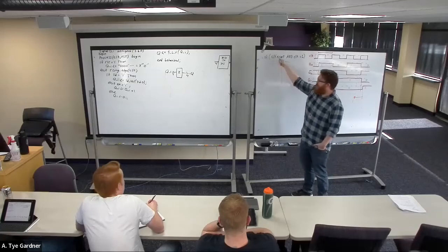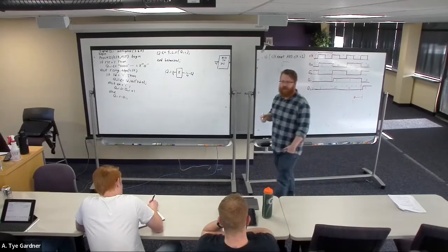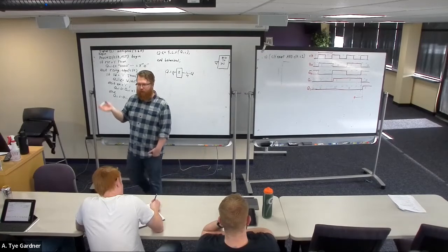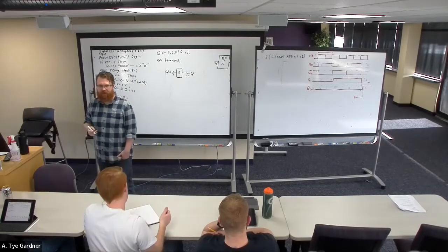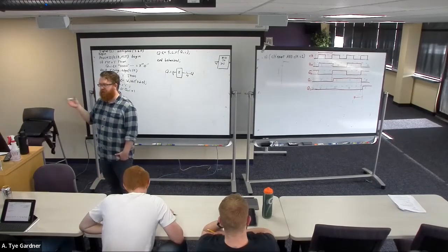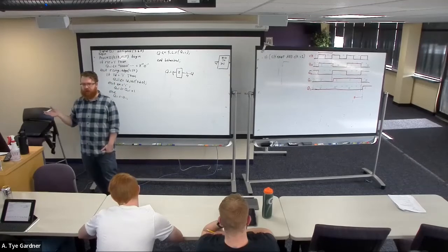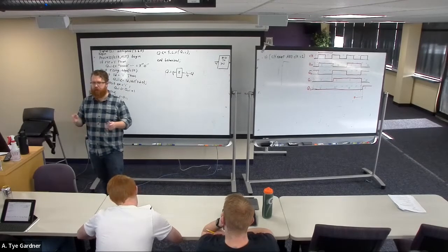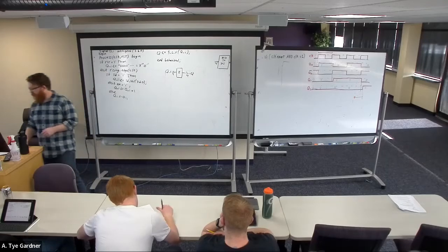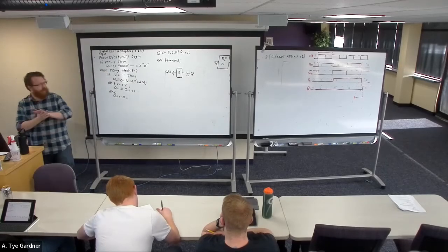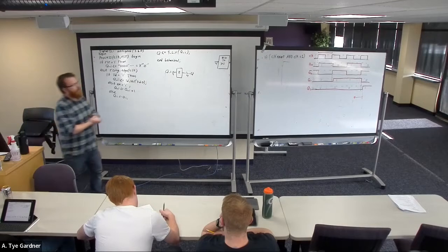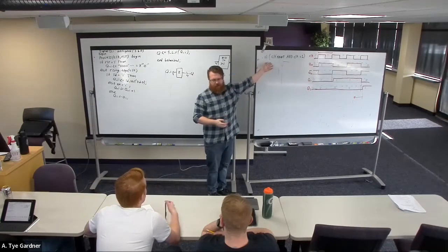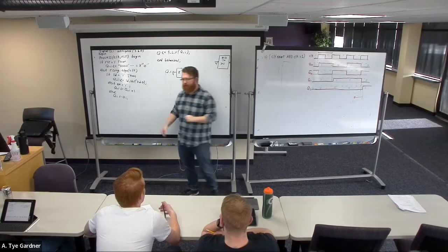There are other properties that we'll learn about that we can access using these apostrophes. You can do things like size: how big is this signal, how many bits are in the signal. If you've programmed much in Python or other languages, you can ask for the size of an array. You have that same kind of thing with these properties. But that comes in a little bit later. I just want you to be aware that if you see this written, you know what it means. I don't write this way because I like just writing rising edge.